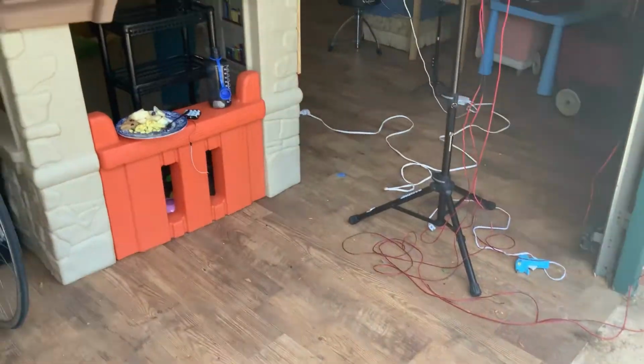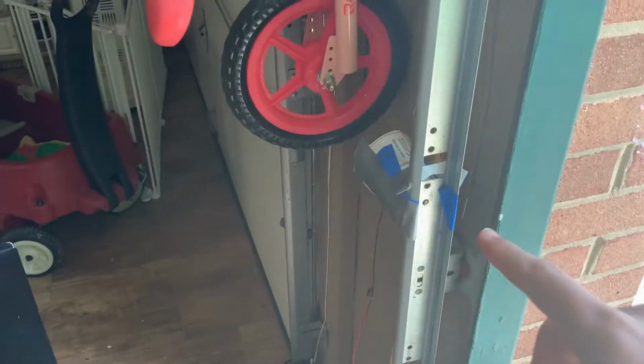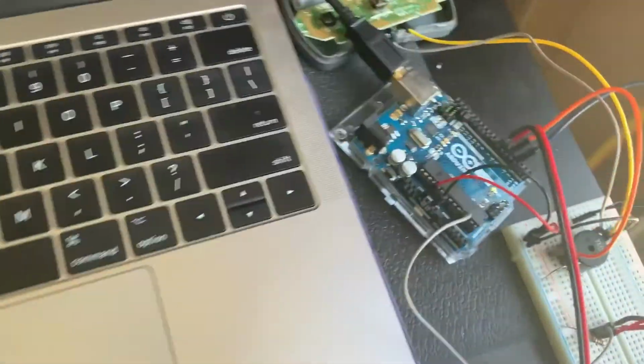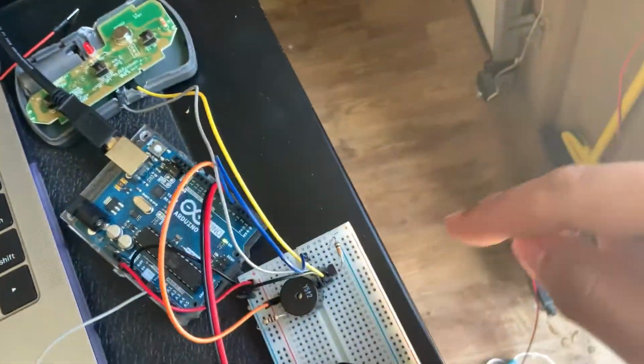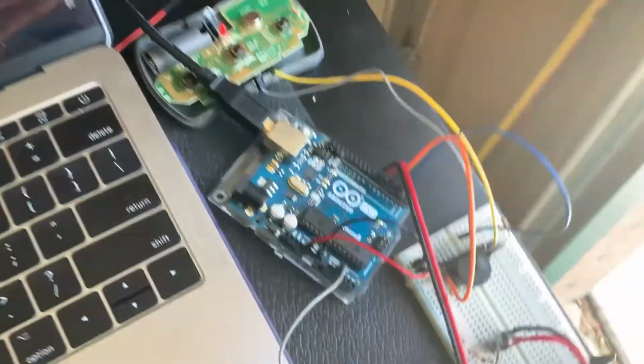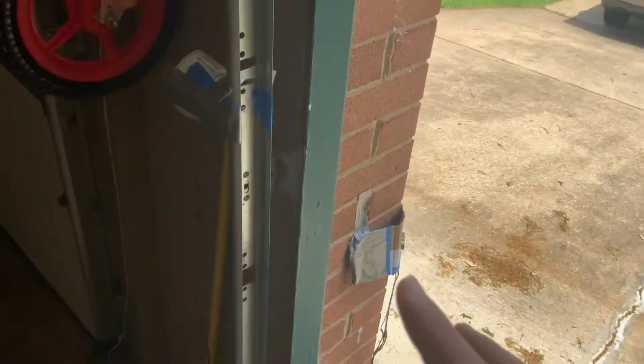For my Lab 9, I automated my garage door using an ultrasonic sensor to detect presence and a photoresistor to detect open or closed. And I used those inputs to trigger the door. I'm hacking the push button for the garage door using a transistor triggered by a digital pin on the Arduino when it fulfills the conditions met by these two sensors.